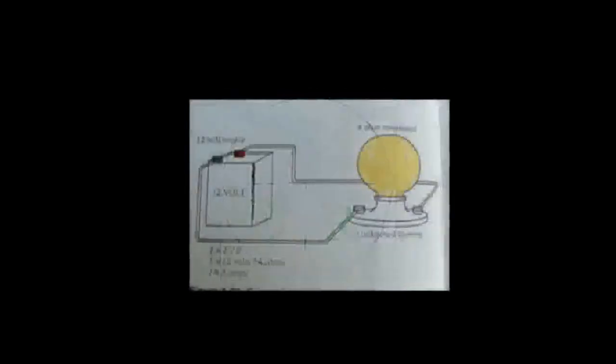Let's look at an application of Ohm's law. In figure 1-22, a lamp with a resistance of 4 ohms has been connected to a 12-volt source. The current is unknown. By applying Ohm's law, you can determine the current to be equal to 3 amperes.